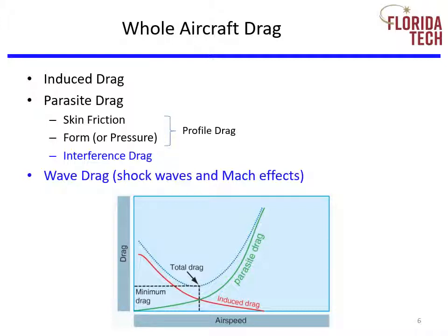There are four basic types of drag: skin friction, pressure, wave, and induced. However, when discussing the whole aircraft, bookkeeping each of these becomes difficult. Therefore, in order to simplify the math, whole aircraft drag is divided into three main components. First, drag due to lift. Second, drag not due to lift. And third, drag due to Mach effects.